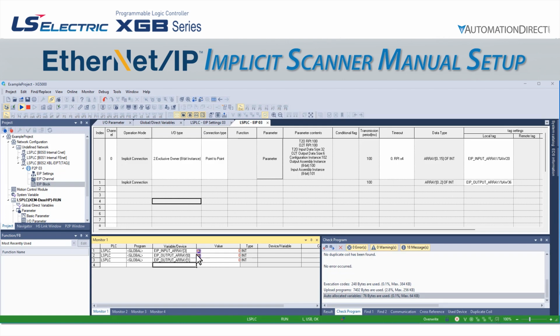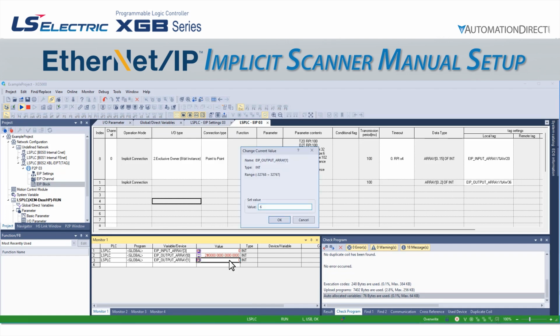We see that currently our actual frequency is 0, our target frequency is 0, and our command data word is also 0. Since the command word is actually a bitmap, let's right-click on that line and select Represent in Binary. This will show the status of each bit in the 16-bit word. Let's set our target frequency to 6000, as this corresponds to 60 Hz. Let's turn on bit 1, the second bit of the command word,